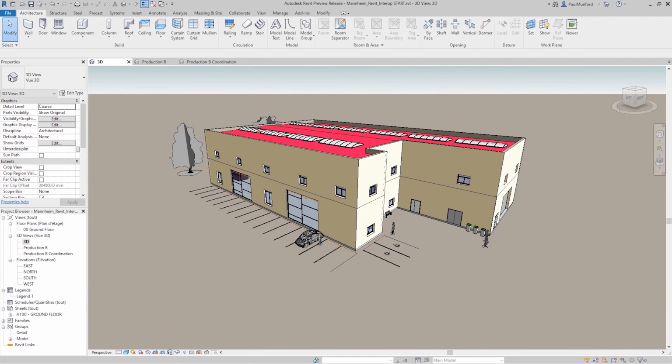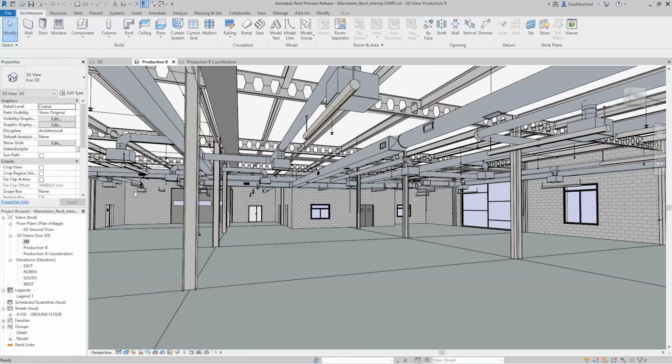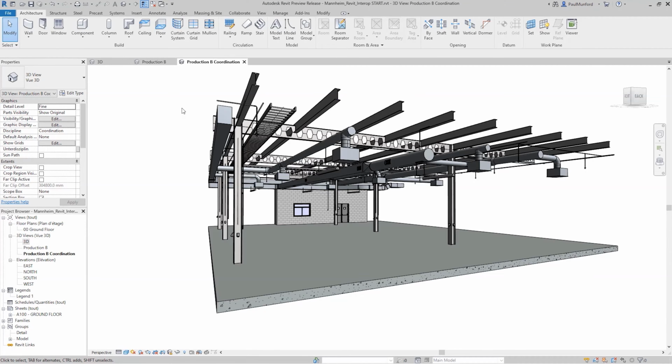Let's start here in Revit. Here is the complete building that we'll be working in. We can also see a view of the area of the model where we'll be placing our equipment. We'll come back to this later. The Revit modeler has created a view of the model which isolates just the area we'll be working on in Inventor. This is helpful because it will reduce the load on Inventor while we work on the design.